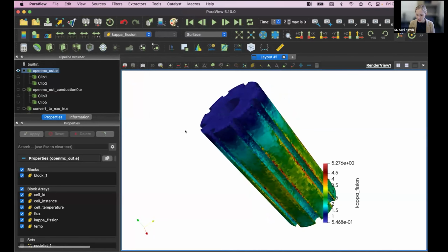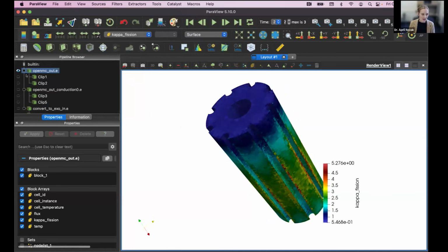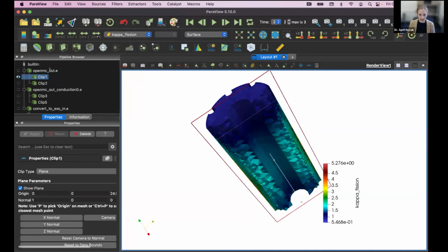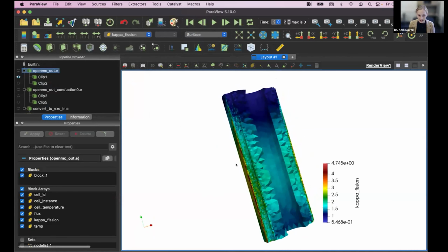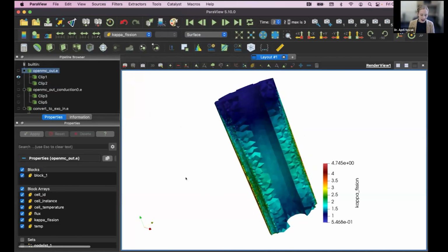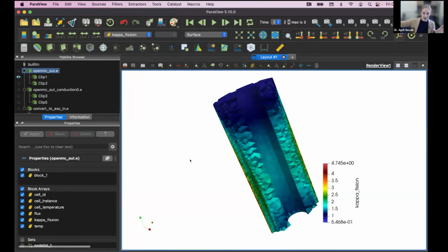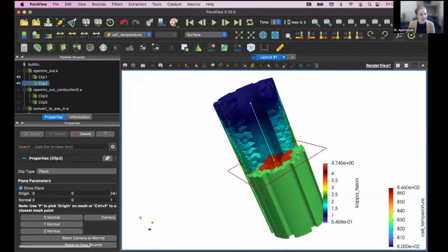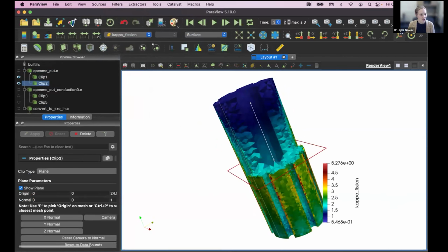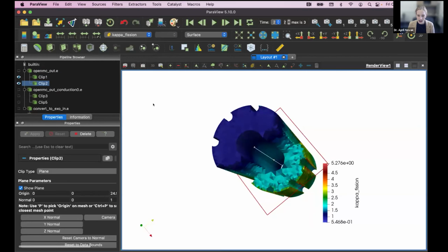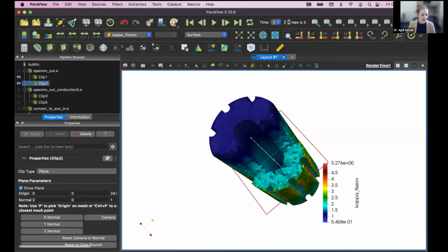Okay, so this is the mesh tally coming from OpenMC. This is the kappa-fission score. This is the recoverable energy release from fission, assuming it's all deposited locally, where the fission event happens. I can see it's very peaked along the periphery from the reflector, reflecting back some neutrons. Remember, there's a CSG geometry outside of this big DAGMC component. I can take another clip and put them both on kappa-fission. And so I can see now the power that's coming from OpenMC.